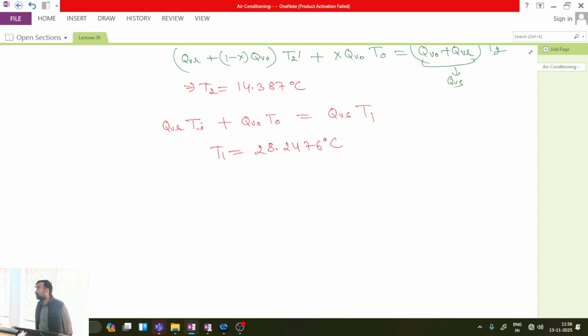So all of you have understood the concept of effective room sensible heat factor. Basically the idea is effectively how much sensible heat load is coming on the room. Because we have done the recirculation and ventilation, the external amount which has bypassed comes as an additional direct load on the room. Is this point clear? And this is a very simple way to calculate this question. If we do not know the effective room sensible heat factor, then we need to follow iterations, which will be an excessively complicated process. Okay, so we'll stop.